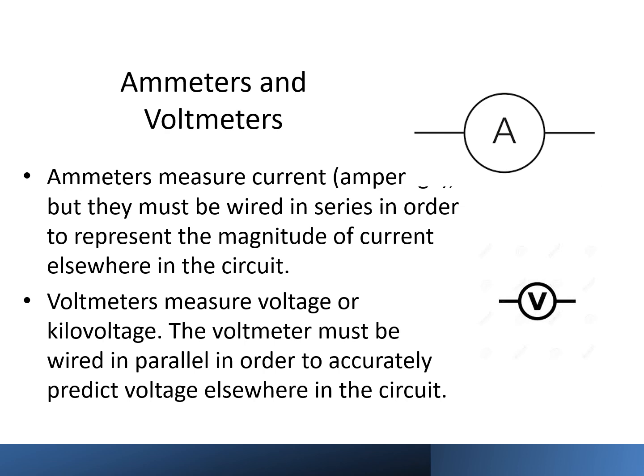And what you do is you just wire in an ammeter, so that the current before it reaches the X-ray tube or before it exits the X-ray tube, well, actually just after it exits the X-ray tube. God, that's a tongue twister. The ammeter wired in series back to the power supply will report a current flowing through it. The current that's wired in series predicts the current of all other circuit elements that are wired in the series arrangement with that ammeter.